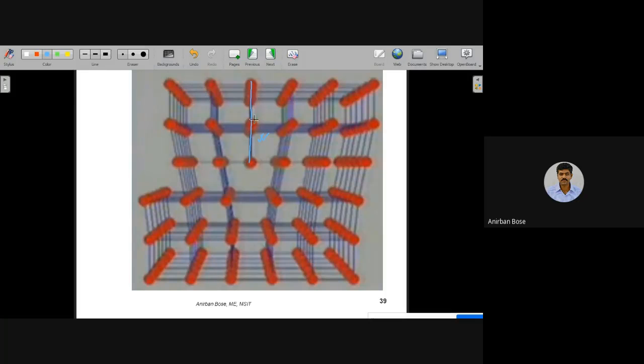Okay, so this is what is called the part plane. Okay, this is a part plane or incomplete plane, part plane or incomplete plane. Okay, so the edge of the incomplete plane, the end of the incomplete plane, that is the line EF, the edge of that plane. That is why the name is edge dislocation, because that is the edge of this line. That means that particular line which is the edge of this plane. Okay, so this is the edge dislocation.